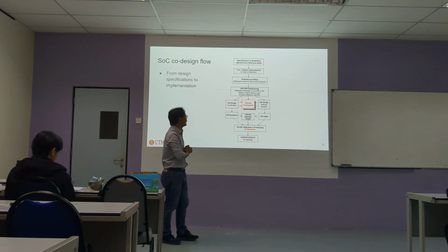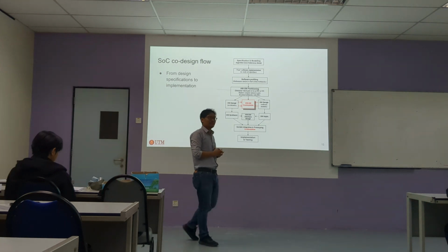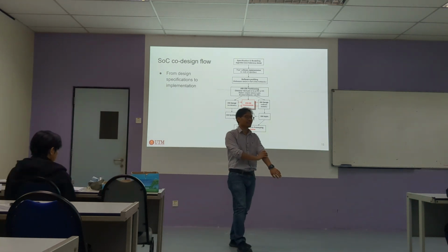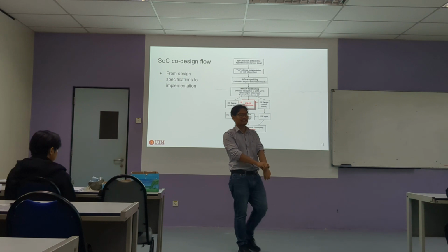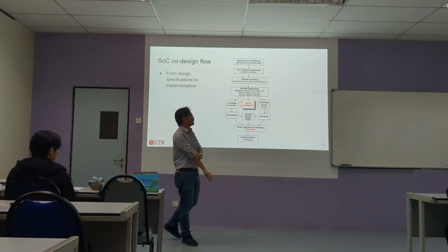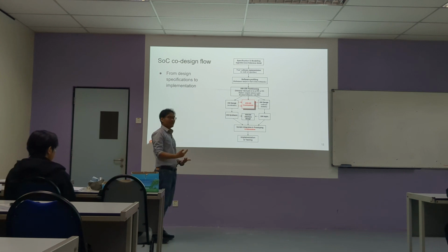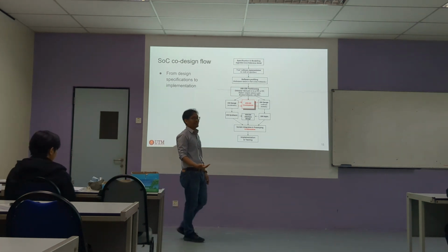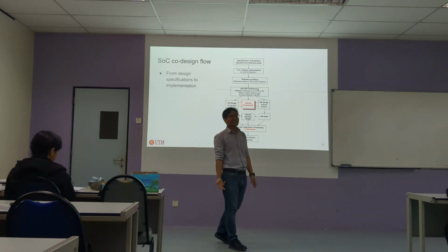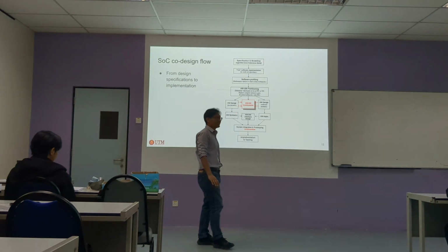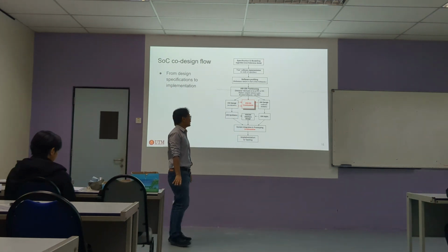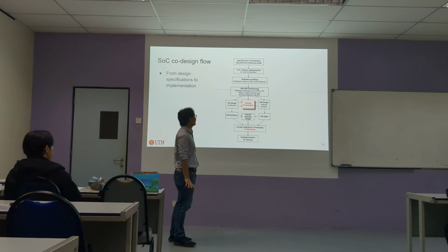There are some tools to convert Python to C, and even Python to Verilog, I have seen some tools, so you don't really have to write manually. But in any case, you will start with software if it's something complex. If it's something easy, you can straight away write the RTL. But even for a sorting algorithm, you start with software first.